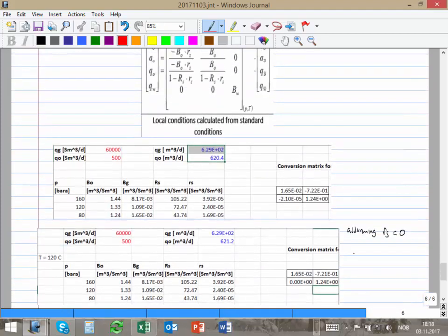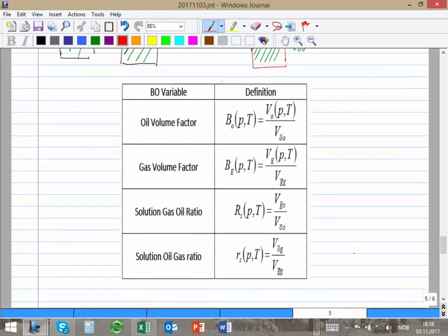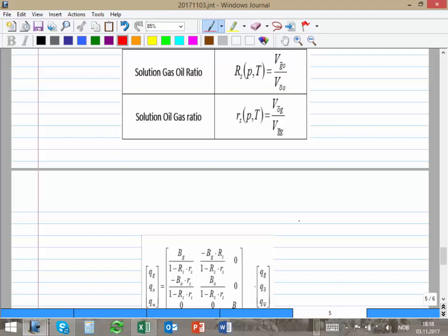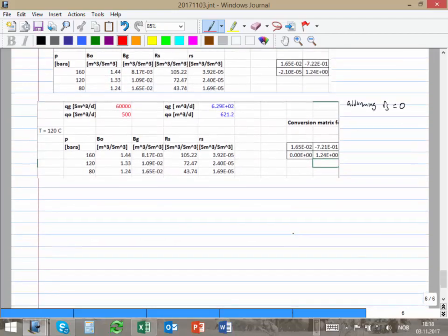This is a complexity that production engineers have, that we actually have to calculate black oil properties at P and T. For reservoir engineers, they really take the T out of the equation, and pressure is the only dependence we have. So that's why I don't like to talk about solution gas oil ratio or formation volume factor. I say just BO, BG, RS, and finished.